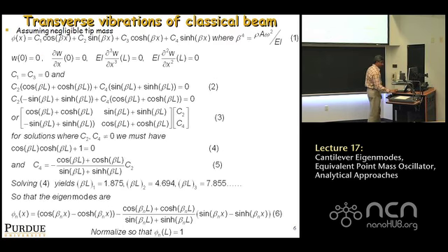This is where now we go into the boundary conditions, okay? And so we're going to do the simple boundary condition, which is to say that the tip mass is 0. So on the left-hand side, where the beam is clamped, W(0) is 0, which means the deflection is 0. The slope is going to be 0 since it's flush, there's no bending slope. So on the right-hand side, we neglect tip mass.